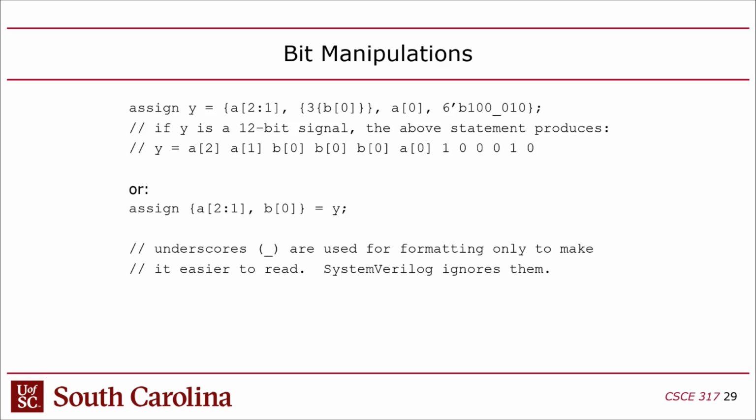One of the questions about PWM is, you've got the duty cycle, but then you've got the period or the frequency, and what should the frequency be? It's what the load needs, and the load varies. It depends on the application. That's the reason, in case you're wondering, that in lab 2 I asked you to be able to control that.